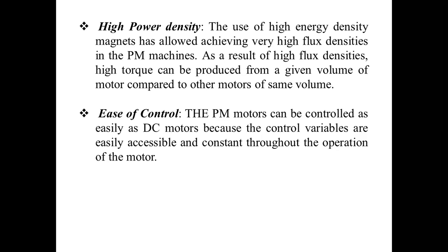The high energy density or high power density magnets have allowed achieving very high flux densities in the permanent magnet machines. As a result of high flux densities, very high torque can be produced from a given volume of the motor compared to other motors of the same volume. That is the major difference.